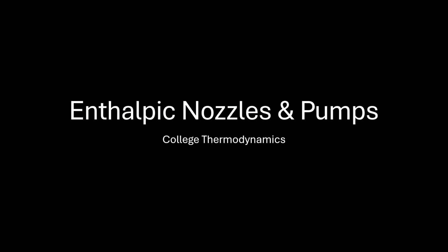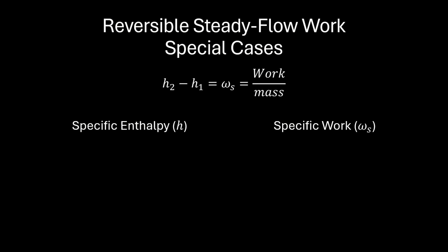Hello, welcome to our thermodynamics video on nozzles and pumps, certain parameters that we will measure, specifically getting into enthalpic nozzles and pumps. Here, what we're going to be basing our premise on is the reversible steady flow work and the special cases where we can take the definition of specific work, omega S, which equals the difference in specific enthalpies between the final conditions and initial conditions of our processes.